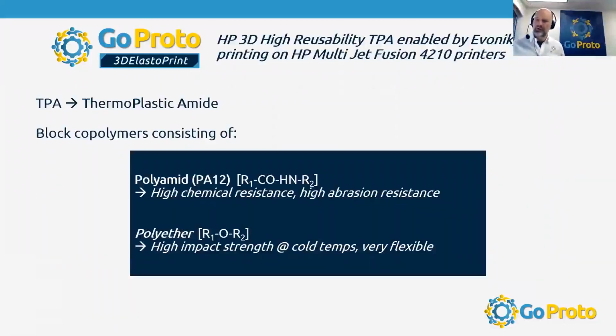Something that's very important to note is that this is based on the PA12 material that we already run. Our printers in San Diego, we're running the Evonik PA12, and the TPA processes quite similarly to the PA12, which is important. Our workflow is not significantly impacted by switching materials. We can still run through very similar print times, very similar build times.